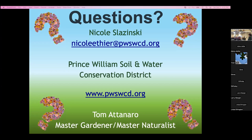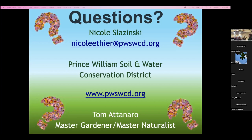recommend then? I guess you said planting water-loving plants, but you don't technically have a rain garden. Possibly. I would do the infiltration test first, because if it passes, you can do a rain garden. If it's really wet, there are other practices I didn't get into, like installing a dry well, which will temporarily hold all that water and then let it slowly recharge the groundwater.